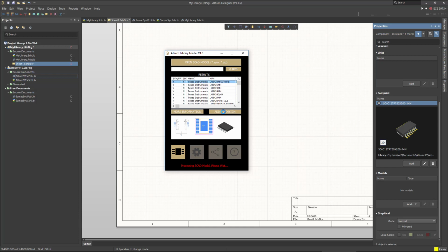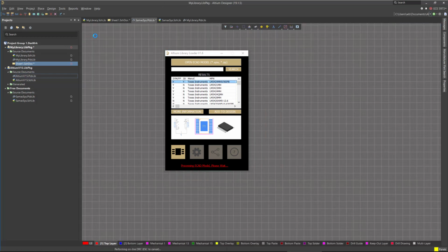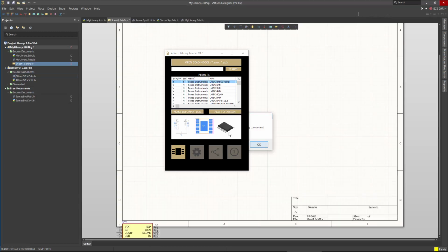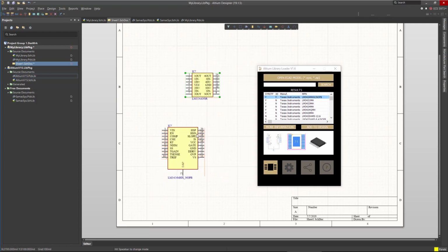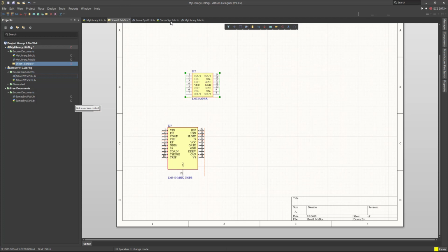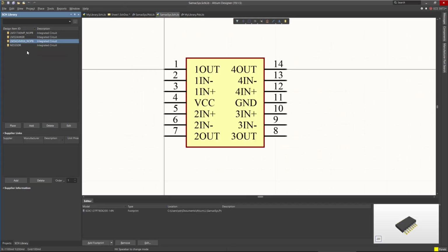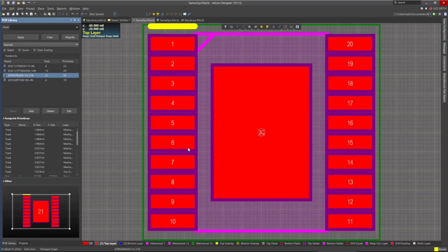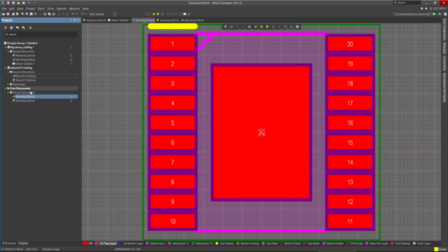If you click add to the design, basically this library will be added into it, like a local library for this loader, called SamacSys. This is the library for this loader, and it's a local library. And here is the component again in different formats. Let's close this one. Now all you need to do is copy the component, this is the component we created, and copy the footprint for that component into your library. Or you can keep this local library for this loader, compile it, and use it as it is. So this is the other way.